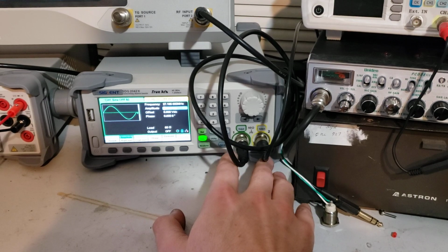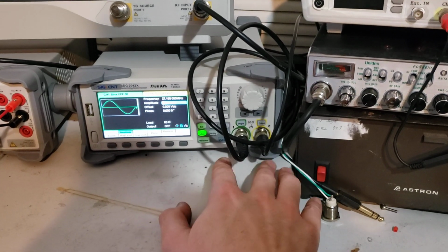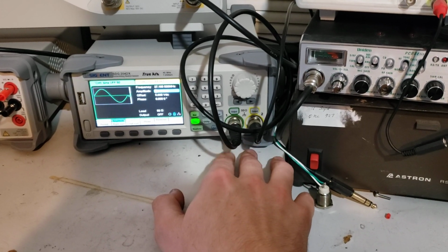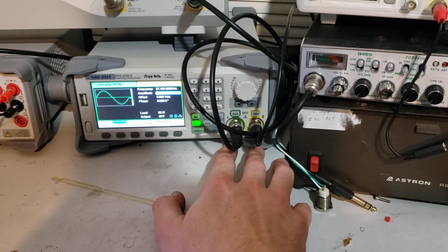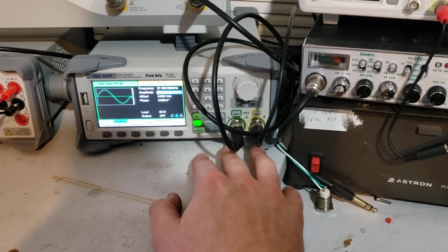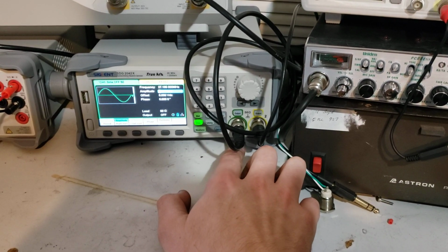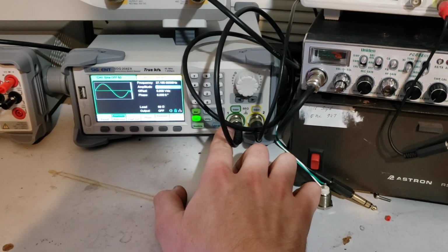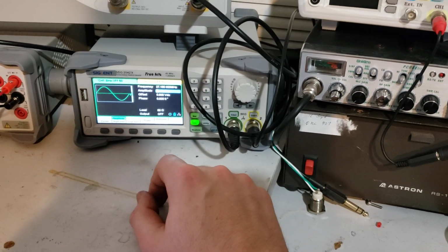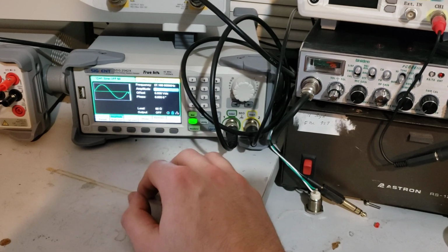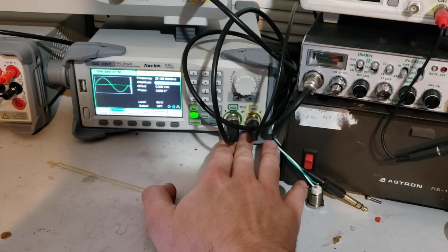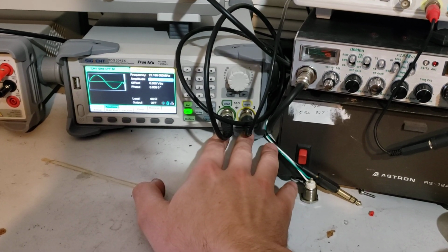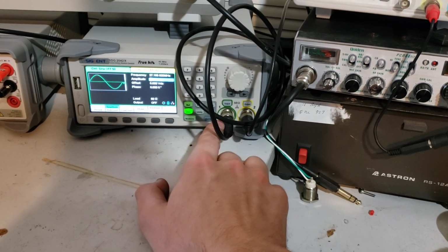And this is a project all by itself, because the power that this puts out at HF frequency ranges is only about 0.06 watts. So I'm going to build a pair of amplifiers, one for this channel and one for that channel, that takes that 0.06 watts and kicks it up into the 10 or 25 watt range. So between 25 and 30 dB of gain for each one of those amplifiers. And their only job is to be a continuous carrier. So these outputs are only going to be continuous carrier.